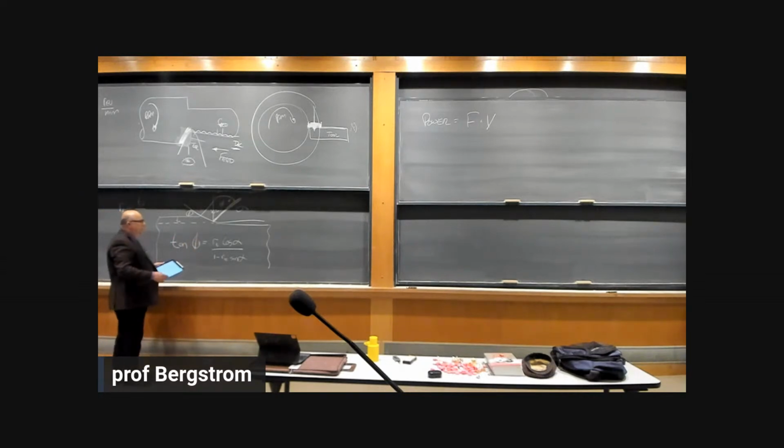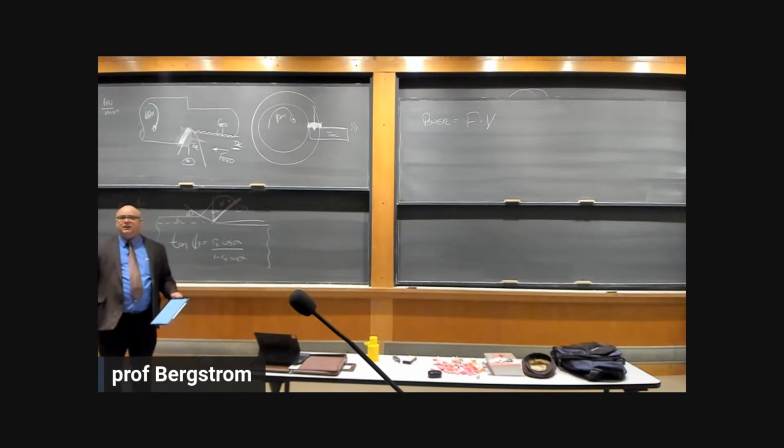And from that, by observing, this is where the science part comes in. We do experiments, and we vary rake angles, and we vary materials. We can learn about the bulk properties of the material so that we can then use that information to predict what the forces would be in the future.